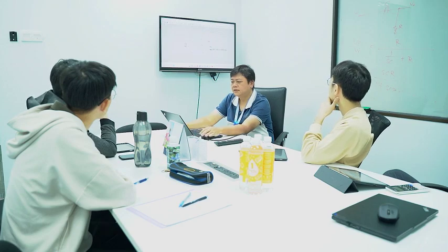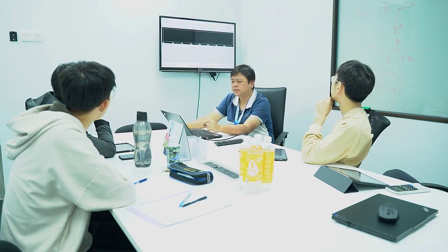So remember the cut-off frequency? 1K, how accurate? 166 kilohertz or 166 hertz? 166, right? Okay, never mind. No, 159. The analysis is just AC analysis, so type is decade, 100 points, starting from 1 hertz to maybe 100 meg, right? After I do a simulation, okay, come out. So plot the output signal here.